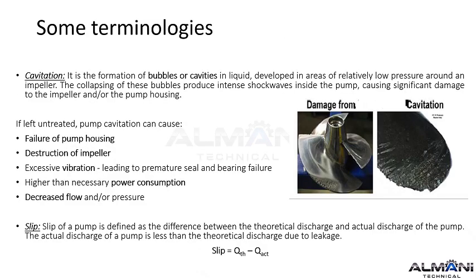Let's cover 2 crucial terms. First is cavitation. This is the formation and violent collapse of vapor bubbles in low-pressure zones around the impeller. The implosions create intense shock waves that erode metal, destroy the impeller, cause severe vibration, and drop performance. It's a destructive phenomenon you must prevent.